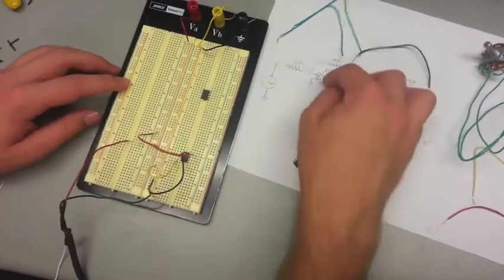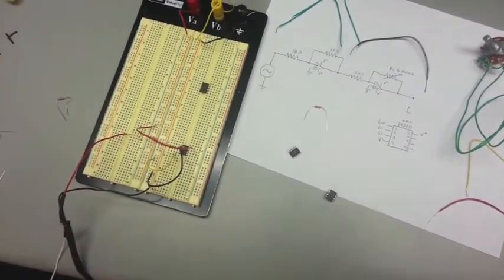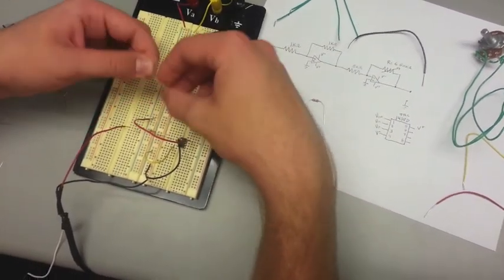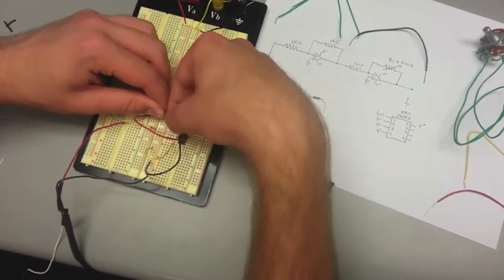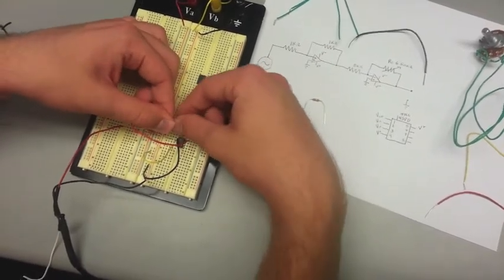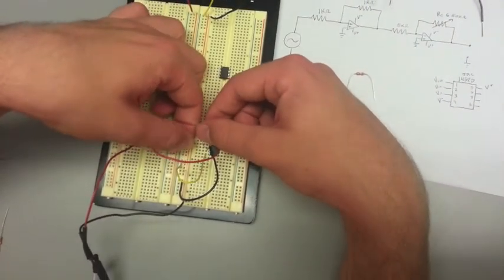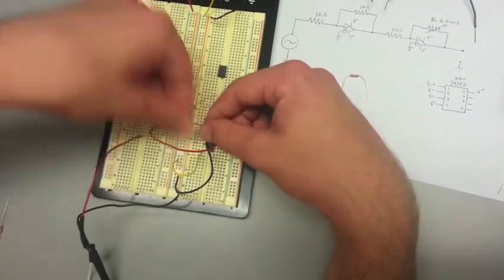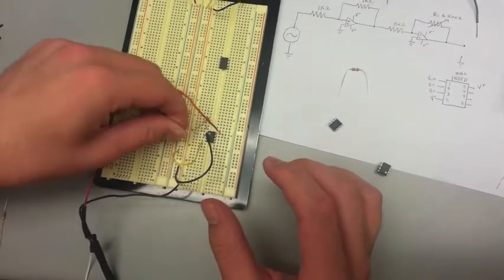And so we've set up the op amp so far, and now we just need to put the feedback resistor in. For the first feedback resistor, it's 1 kilo ohm. So you go from the V out to, actually, the same row as the 1K ohm resistor is in. It's a really short hop, and you just kind of bend the resistor out and pop it in. And we're going to move over the 1K ohm resistor just to make it easier on us. Like so.